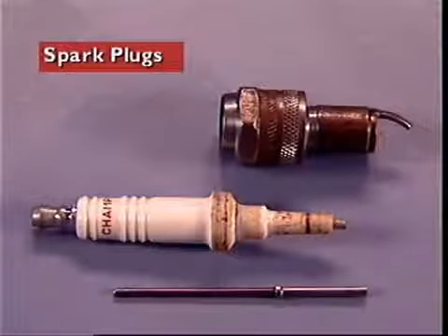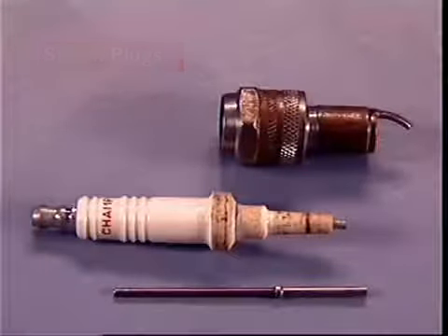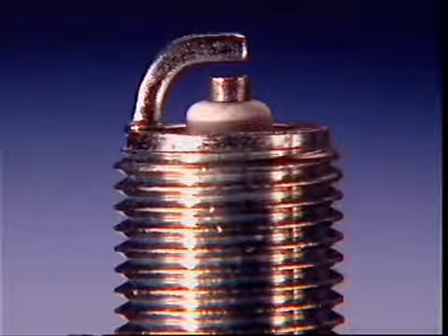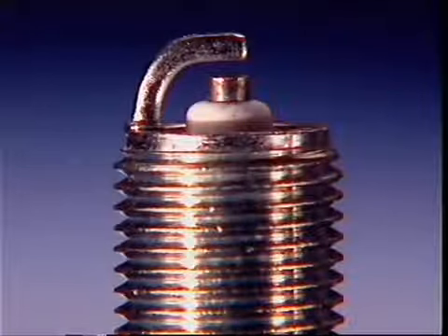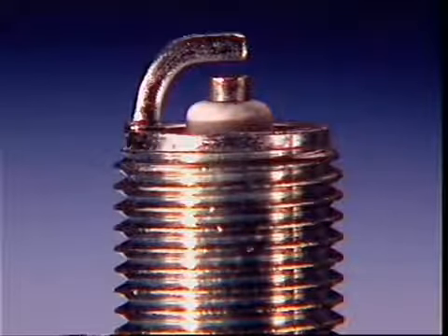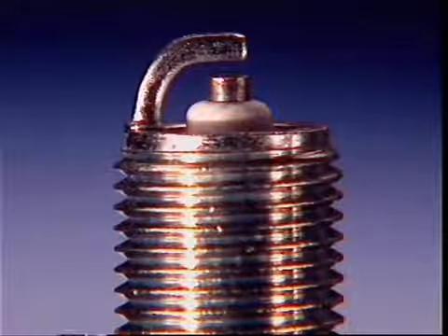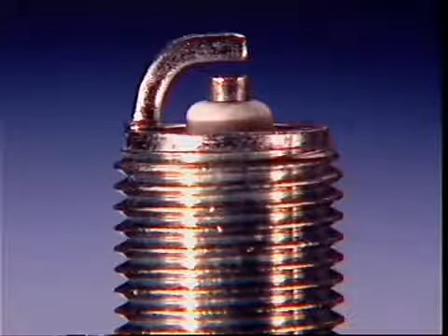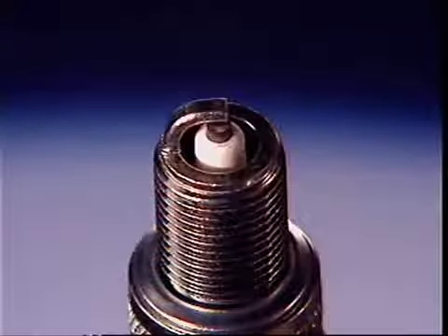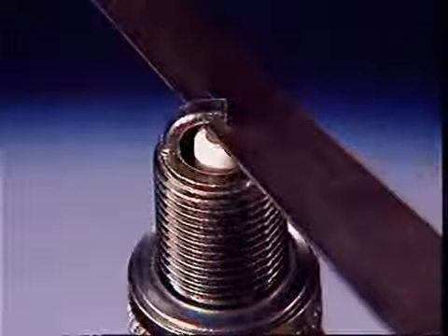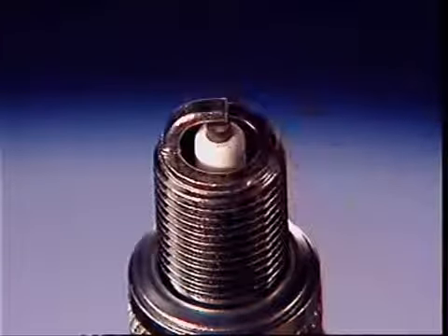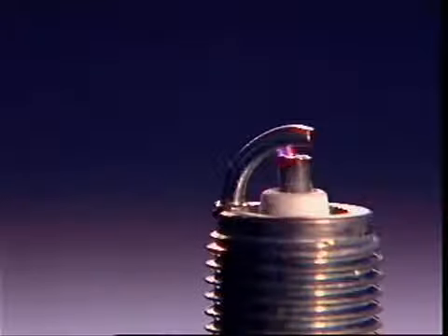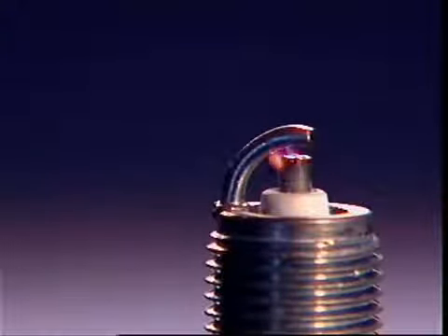The spark plug consists of a plated metal shell with a ceramic insulator and an electrode extending through the center of the insulator. Threads on the metal shell allow it to be screwed into the cylinder head, and a short earth electrode attached to one side is bent in towards the center electrode. The electrodes are of special alloy wire with a set recommended gap between them. The spark bridges this gap to ignite the air-fuel mixture in the combustion chamber.